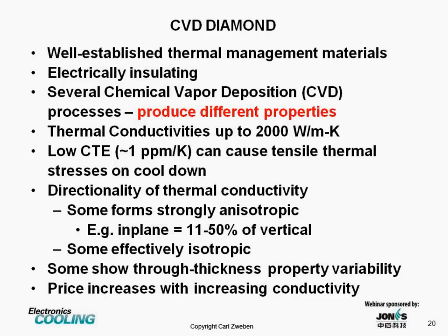CVD diamond has a CTE of about 1, and that can cause tensile thermal stresses on cool down in semiconductors and ceramic substrates. But we'll see that there may be ways to deal with this when we get to the applications charts. It has been noted that there may be some directionality of thermal conductivity.